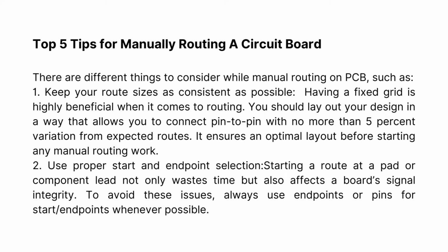2. Use proper start and endpoint selection. Starting a route at a pad or component lead not only wastes time but also affects a board's signal integrity. To avoid these issues, always use endpoints or pins for start/endpoints whenever possible.